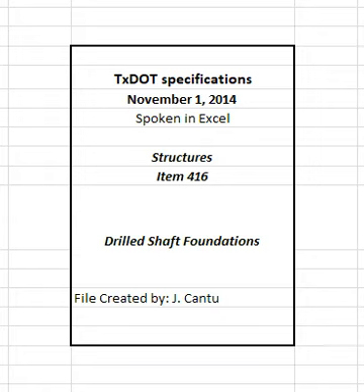Tie spiral reinforcement to the longitudinal bars at a spacing no more than 24 inches, or as required for a stable cage. Ensure lateral reinforcement is not welded to longitudinal bars unless otherwise shown on the plans. Center the reinforcing steel cage in the excavation using approved roller-type centering devices unless otherwise approved. Use concrete or plastic chairs to keep the reinforcing cage off of the bottom of the hole.